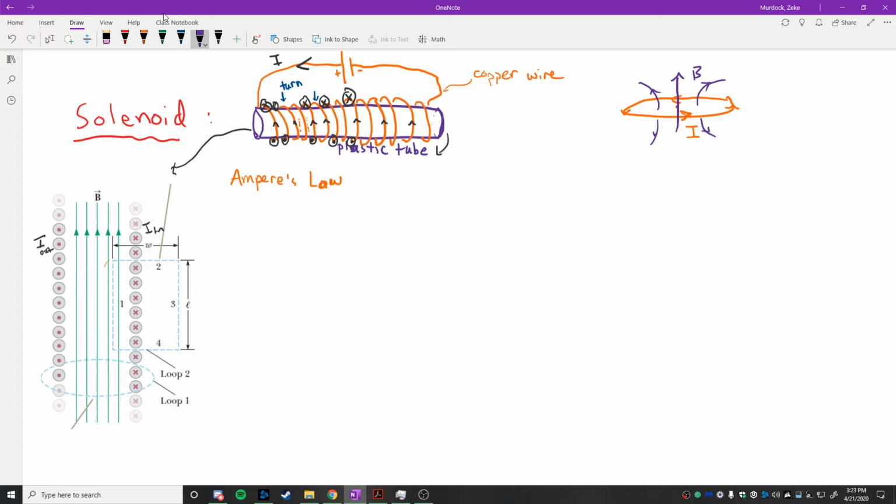Because when you start to stack a bunch of these together, these kind of loopy features of the magnetic field, well, they kind of start to disappear. If you get enough of these loopy magnetic fields lined up together, then you're going to get a nice straight magnetic field pointing through the center, right? If every one of these loops produces a magnetic field at its center like this, and then you just start stacking loops together, I stack another loop exactly like this below it, and then another exactly below it, you've got this series of rings.